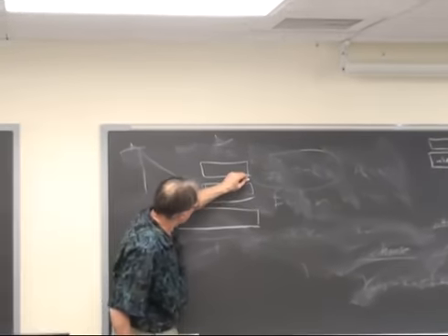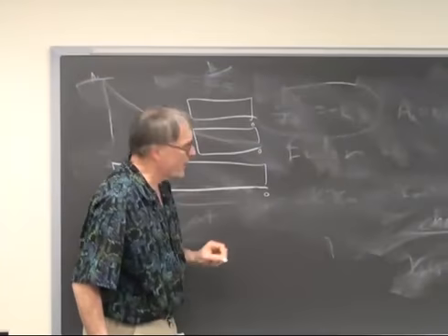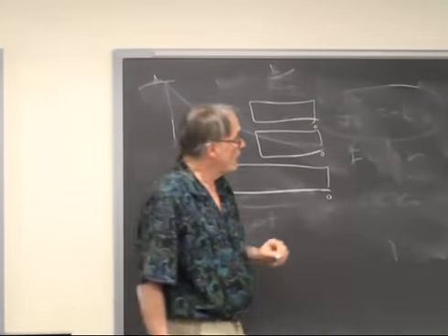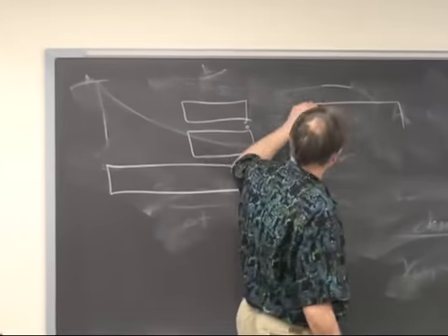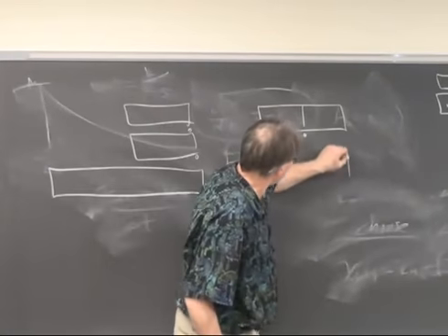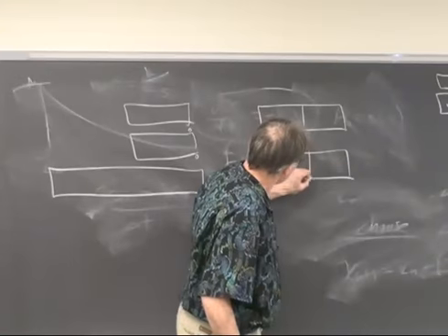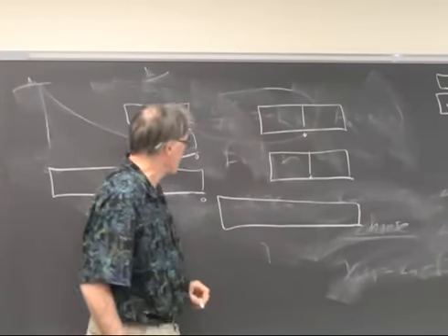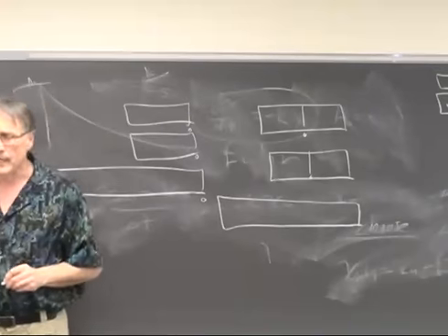And in our thinking, the binary point is there. Now for an 8-8 fixed point, the binary point is going to be in the center of the 16-bit field. So we have a 32-bit result. Where's the binary point exactly?